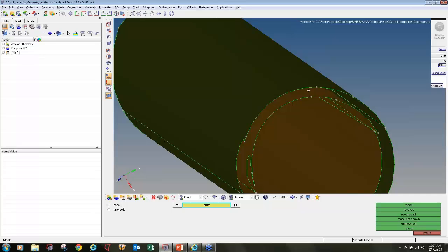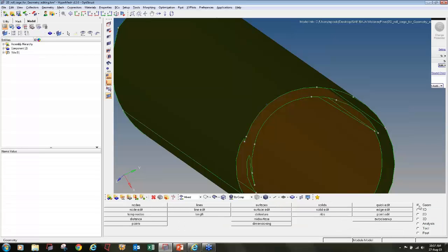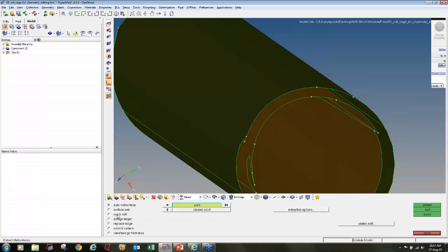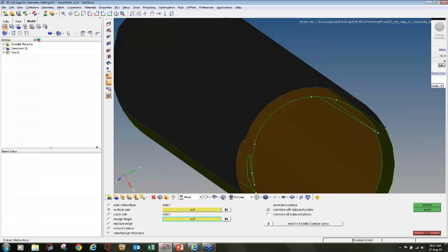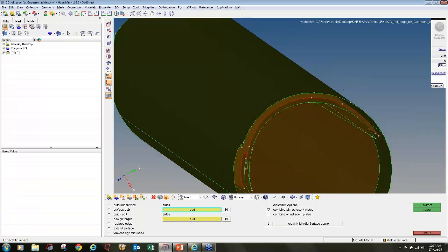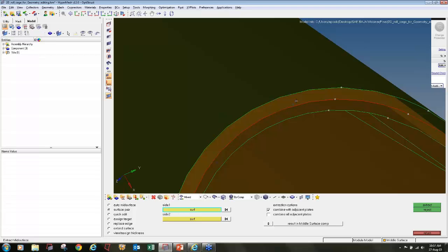That's why I create a mid surface here and do the meshing at the mid surface. I will show you what I am saying. You can see this is the mid surface. So in 2D, if you do meshing, then the element's thickness will go half up, half down. Similarly, half up, half down. So actual thickness, if you use these two surfaces, will get doubled.